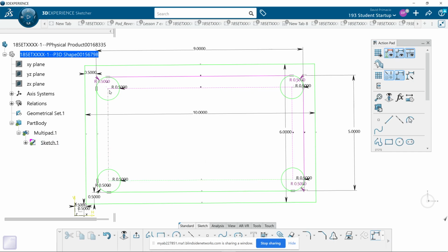What's going to happen is it's going to come along here and it can't just smoothly make the corner. It stops and then starts again. When it stops and starts at that corner, it chatters on that corner, and then you get a dig on these corners that you didn't expect. So what that would mean for me as a guy in the shop, I would have to change this radius or get a different cutter.